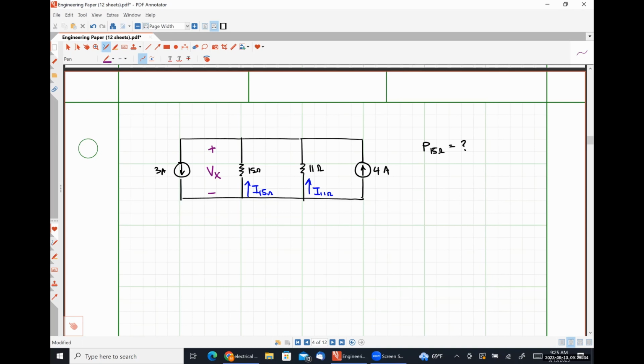Okay. So now let's move along to applying Kirchhoff's current law. Which formulation are we going to choose? Number 1, current flowing in equals current flowing out. Number 2, current entering a node is equal to 0. Or number 3, current exiting a node is equal to 0. Number 3. All right. So KCL number 3. And are we going to apply this at the top node or the bottom node? Bottom. All right.